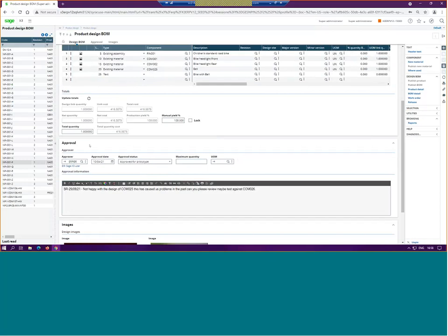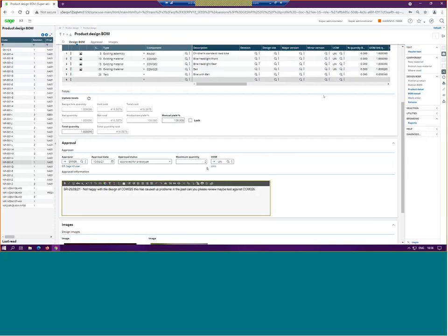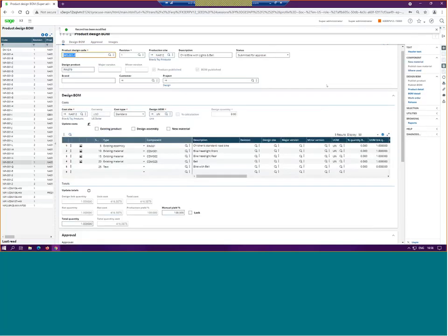One additional field we've now got available to us is this maximum quantity. So for this particular product on a works order, I can specify I only want them to make 2 of this particular item. I don't want them to make any more, because I want to stop someone putting in, let's make 200 of these bikes by mistake. The approver can specify what quantity they want to be manufactured on this works order in the production area. So I've got a design, I'm now going to create a works order for it.